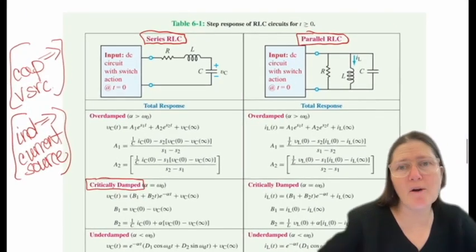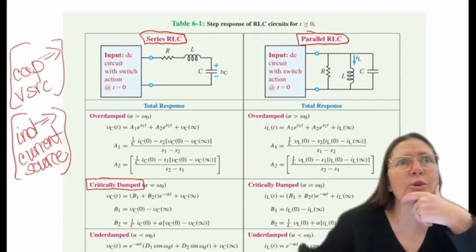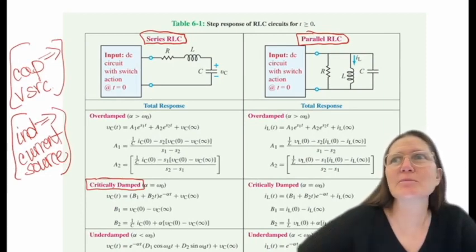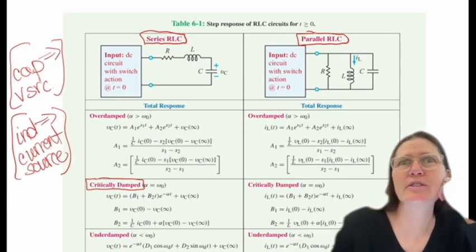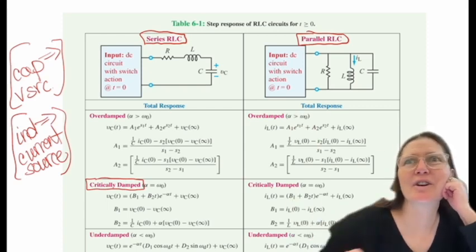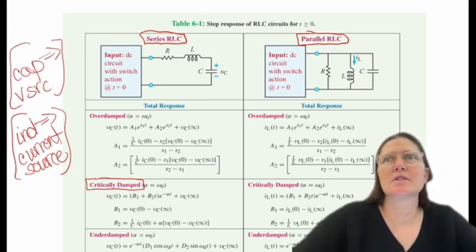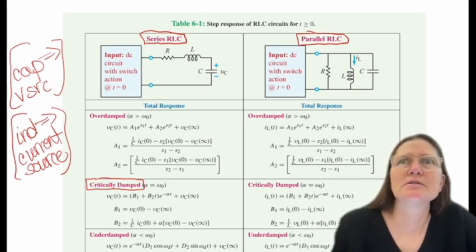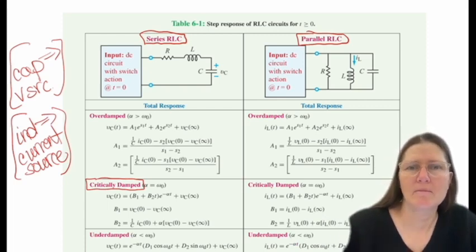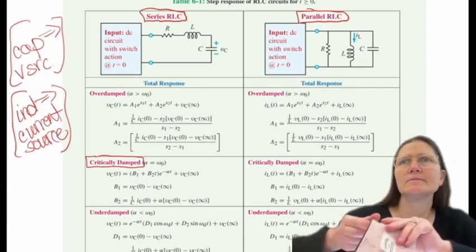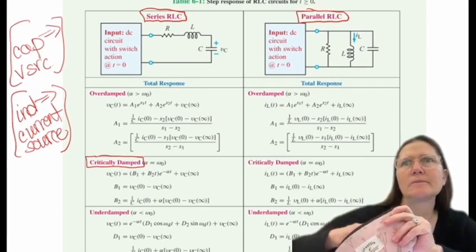Last time we talked about RLC. So anyone want to take a stab at summarizing the procedure to solve for RLC circuits? You take what you already know, and you can use substitutions into those other equations to find the second order differential equation. Then you can solve that and use your initial conditions. You have to note that the voltage on the capacitor and the current of the inductor don't change instantaneously.